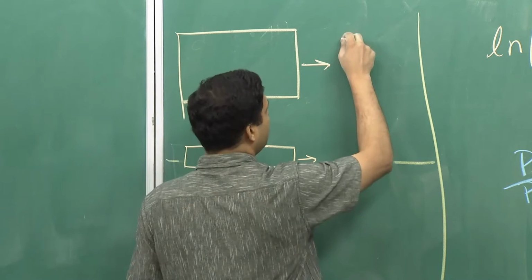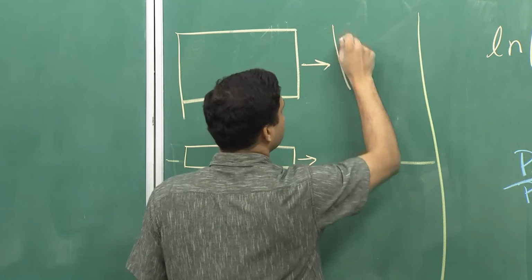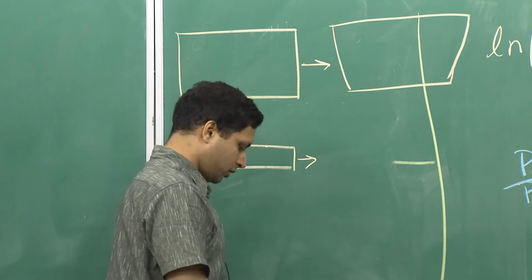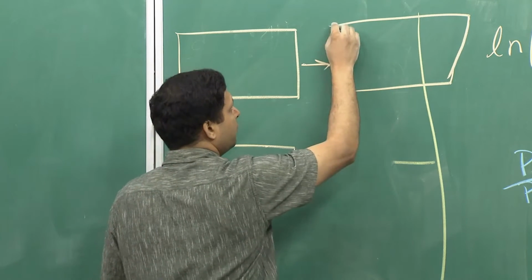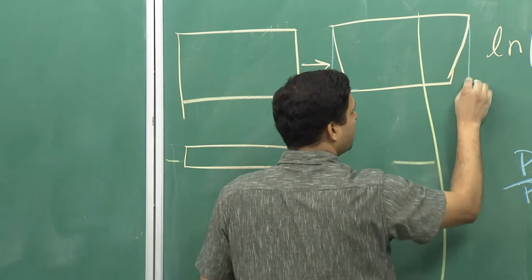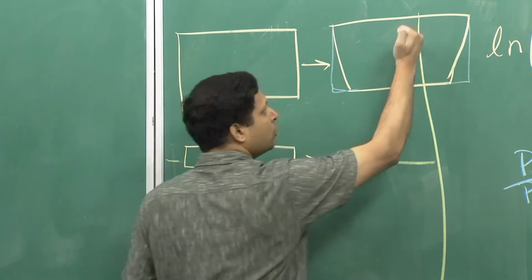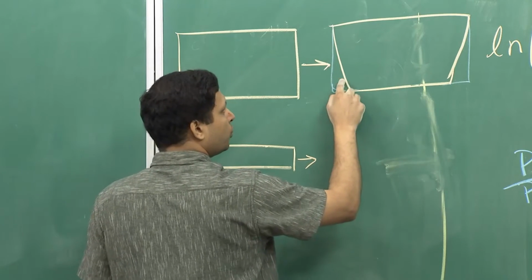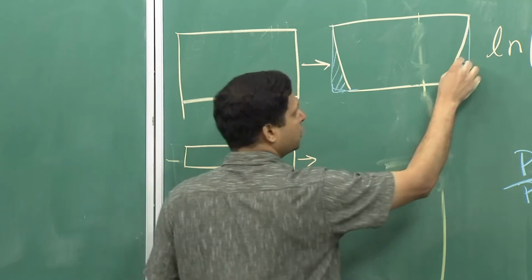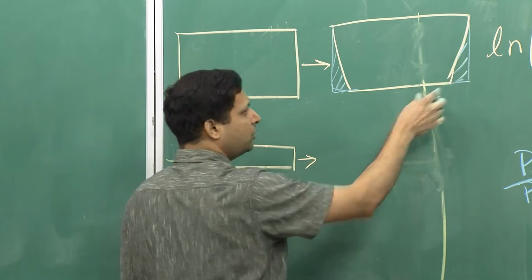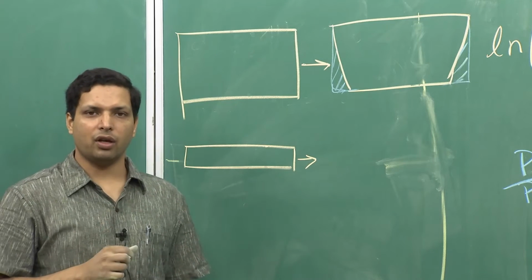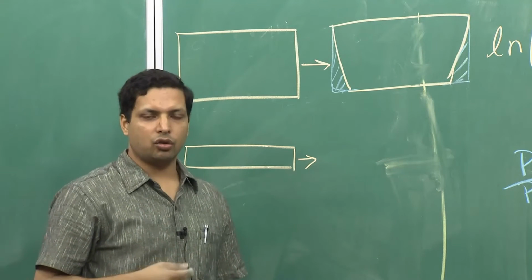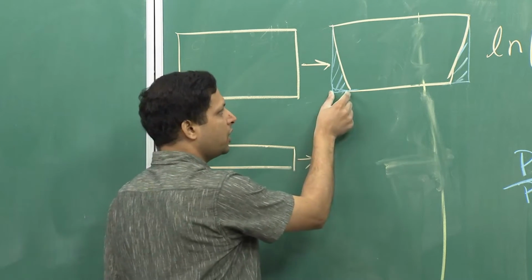So, if you were to sinter this, it will probably shrink something like this. Why have I drawn it like this? Of course I am drawing it in an exaggerated way, and there is no line over here, so let me remove this. What I am trying to show here is that the shrinkage would be larger in the region where the pressure was smaller or the density was smaller. The relative density in this region was smaller, so it was not packed or compacted as efficiently, and therefore, shrinkage here would be larger.